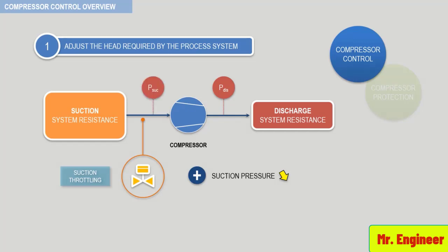Frequently, suction pressure is measured upstream of the suction throttle valve, and the operators are not aware of the actual pressure ratio that the compressor experiences. In summary, suction throttling will control the operating point of the compressor, but will expend less energy and reduce operating costs.